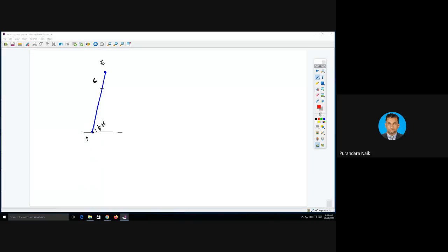Now I have to draw the reference line. This is one reference. What is the angle of force F? This is link number 4, right? F54. What is the angle of F54? 27 degree. Take 27 degree. Alpha is 27 degree. This is F54.